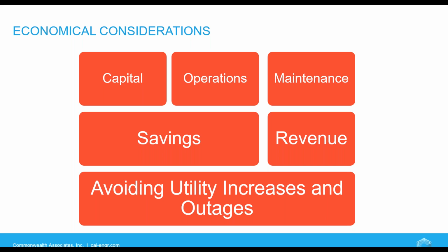For savings and revenue, we look at the energy bill, right? The higher the efficiency, maybe the lower the energy bill. If we can grab that excess heat, use it for HVAC heating, right? Now we don't have to power HVAC units for heat with electricity, right? We don't need to power or heat ancillary systems. So capturing that excess heat will allow us to reduce the need for maybe ancillary equipment in other processes. That's something to evaluate where you might be able to use that heat and save money elsewhere.